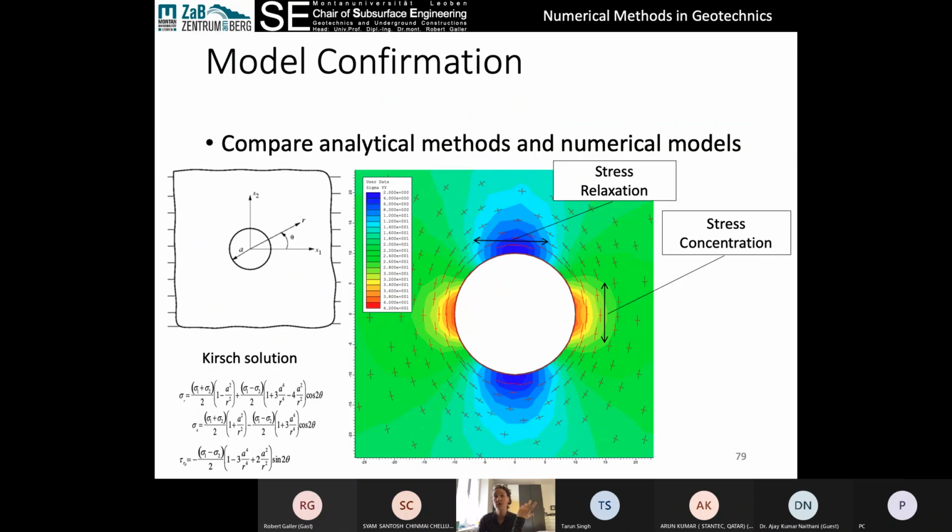Now, of course, if we're in a green field and we don't have a tunnel to compare with, we have to be using different methods to do that. Maybe using another case study to calibrate our model, or using other experiments like modeling a UCS experiment to say, okay, my input parameters are the same as my lab results, so I can use those material properties in my model. So that's the calibration stage.